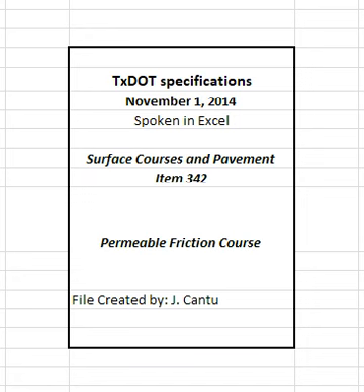When WMA is used, document the additive or process used and recommended rate on the JMF1 submittal. The engineer and the contractor will verify JMF1 based on plant-produced mixture from the trial batch unless otherwise approved. The engineer may accept an existing mixture design previously used on a department project and may waive the trial batch to verify JMF1. The department may require the contractor to reimburse the department for verification tests if more than 2 trial batches per design are required.